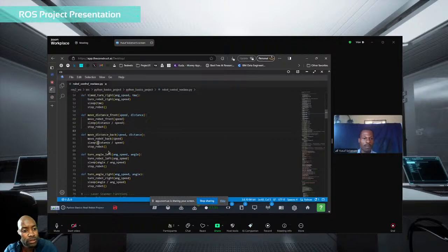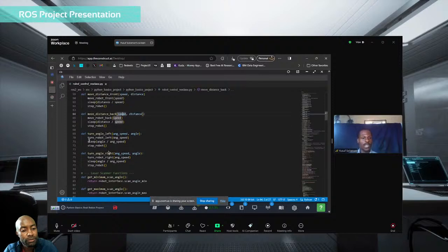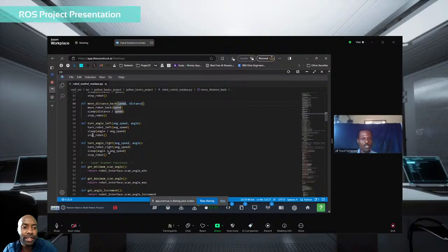Same thing for the back. We calculate the sleep time that we need by dividing the distance by speed and setting the robot's move speed to the particular speed that has been fed into the function as an input parameter. Now, turn angle left. This is like the...